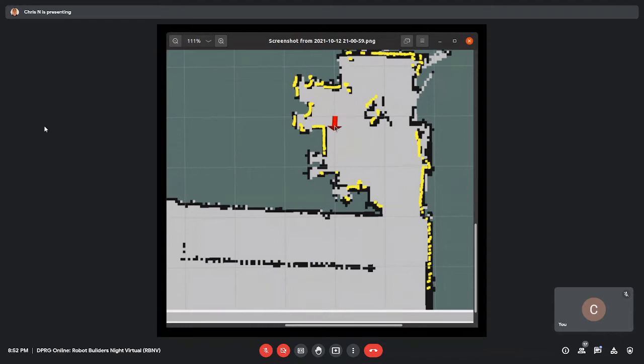It's compensating for all that odometry drift and eventual IMU drift. It's looking at the laser scan, right? That's where the laser comes in, and that's where the map comes in too, either a predetermined map or one generated on the go, with the laser scan matching.